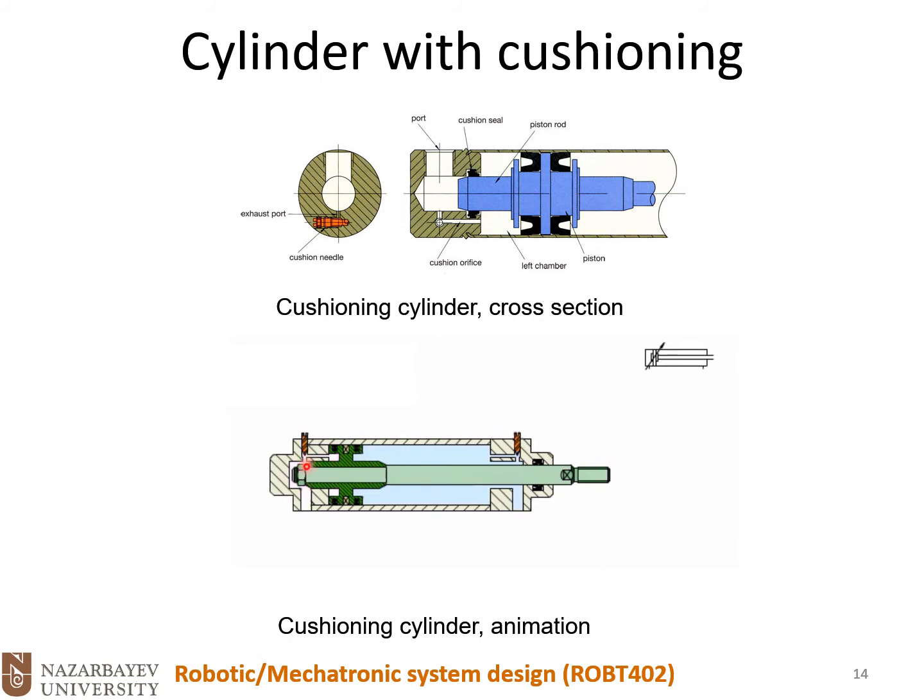But if we close this orifice and close this opening, then the air needs more time to escape from these small chambers. You see the symbol here, so easily you could see those bulges on the piston, and that flash shows that the cushioning is adjustable itself.